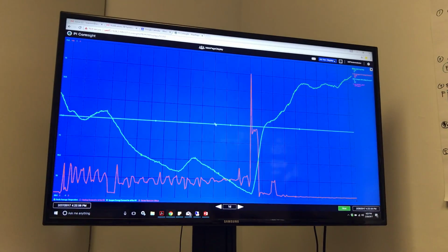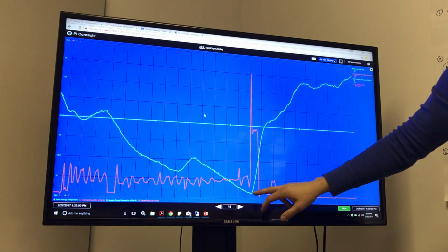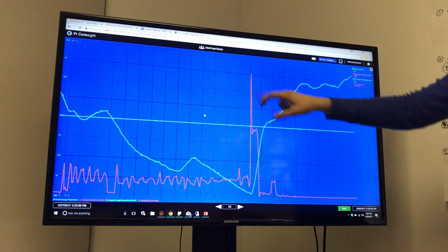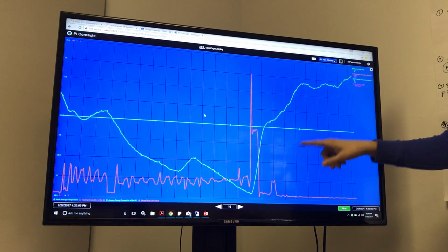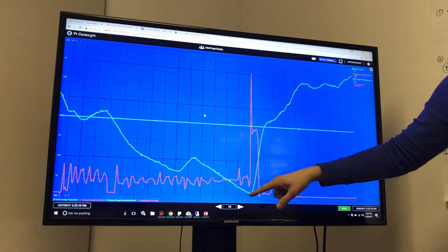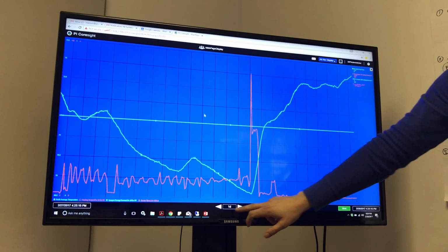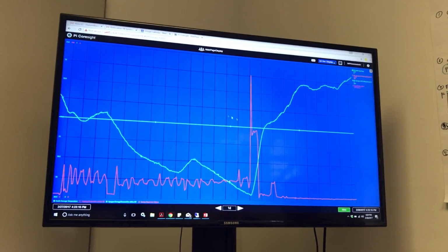So here we'll show you our night setback, the temperature decrease this morning. Green is temperature, blue is cooling, so of course 0. Red is our heating demand, and that's it. So this morning, what's the time step? That's 1 day. So that's an hour. The heating demand was an hour long and then it stopped.